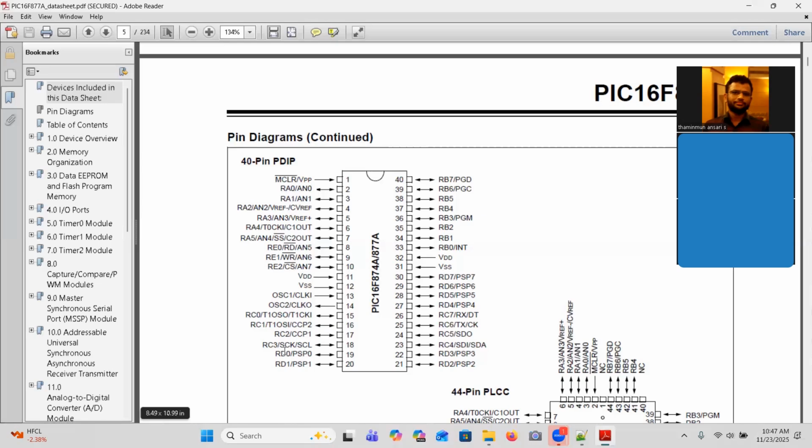The clock circuitry is already there in the microcontroller itself, but it needs a crystal, because they cannot embed the crystal in the chip. They cannot do that. That is not possible. Only passive elements, like resistors and capacitors, these things, and other op-amp related stuff you can build. Gates you can build, but oscillators and inductors, those things you cannot build in a monolithic chip. In that silicon wafer, you cannot build a crystal oscillator because that is a different material.